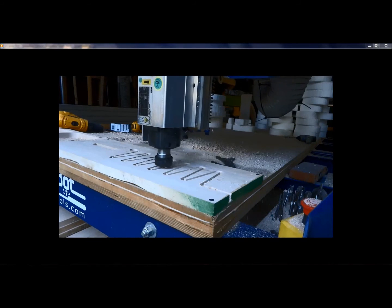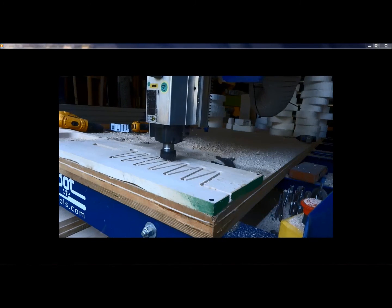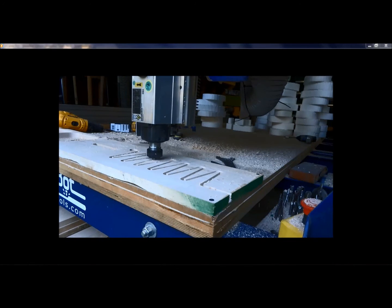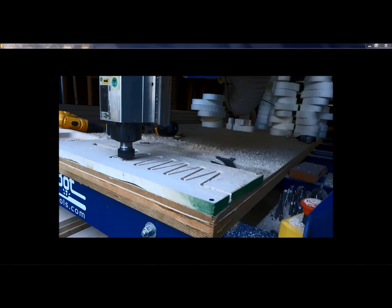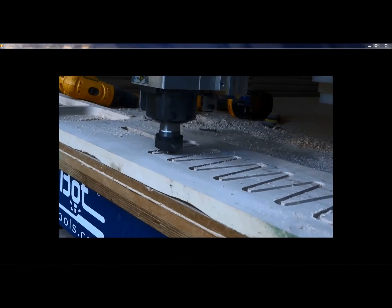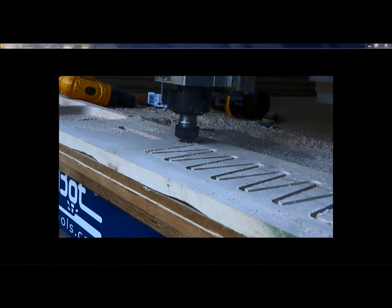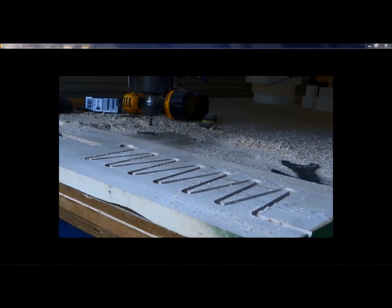But for that to lift up right now, that would damage your finished project, and a small bit like this on hard maple, it will probably end up damaging the bit. But this is a good example of a lead in and a lead out. So we've led in from off the material, and now where we're about to lead out of that cut is an area that's already been pocketed out. So it can just pick right up there. So there's a lead in and a lead out.